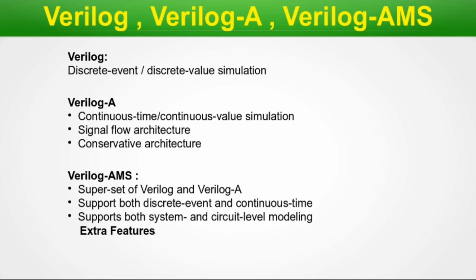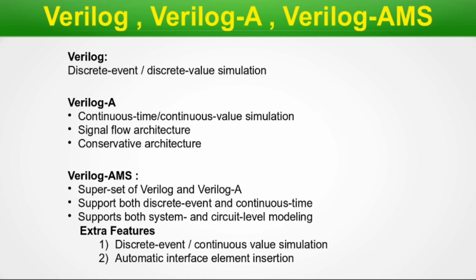Now comes the interesting part. There are extra features in AMS apart from Verilog-A and Verilog. Number 1, discrete event and continuous value simulation. This makes Verilog-AMS compatible to use both the Verilog and Verilog-A syntaxes for simulations. And mostly for this simulation what I am talking about is analog digital co-simulation or analog digital mixed mode simulation. There are multiple terminologies spread over the industry, so anything you can pick up where an analog and a digital are simulated together. The second point is a very important part.